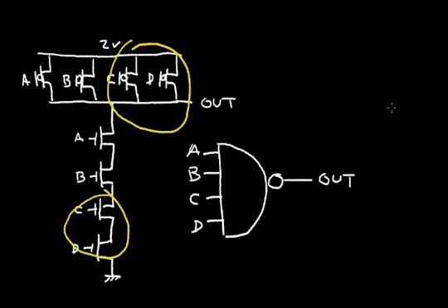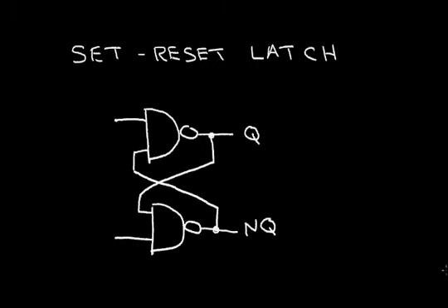So let's consider what we can do with the NAND gate and the NOR gate. So here's a simple circuit using two input NAND gates. Now this is called a SET-RESET latch. And let me label this input not set, and this input not reset. Now, not set and not reset are normally at a logic 1 level. And I'll draw this as a logic 1. And not reset will normally be at a logic 1 level.